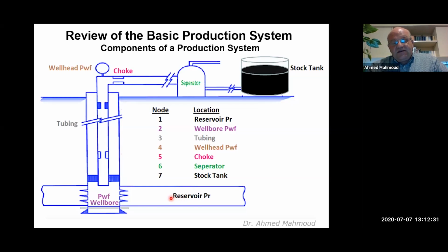And then as you cross this bridge into the wellbore, you pay quite a big amount of delta P, but the flow will move from high reservoir pressure to low pressure in the wellbore. And then this pressure in the wellbore will be motivated to move to the wellhead because the wellhead pressure is going to be adjusted to be lower than the actual wellbore pressure.